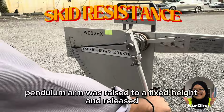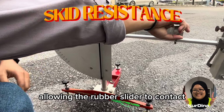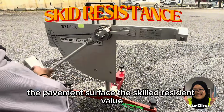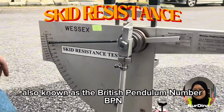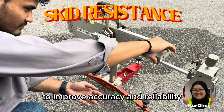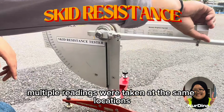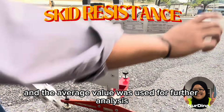The pendulum arm was raised to a fixed height and released, allowing the rubber slider to contact the pavement surface. The skid resistance value, also known as the British pendulum number (BPN), was recorded directly from the scale. To improve accuracy and reliability, multiple readings were taken at the same locations, and the average value was used for further analysis.